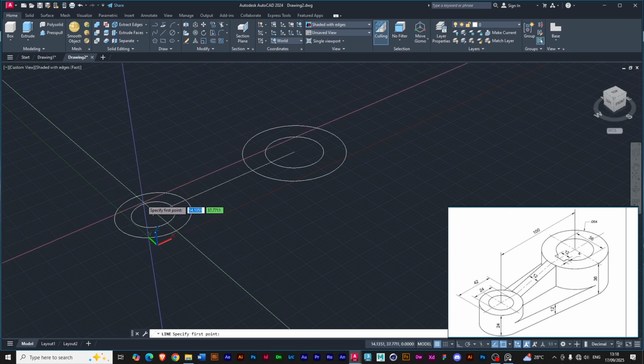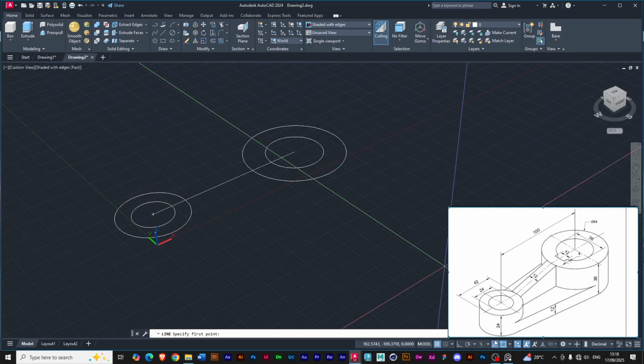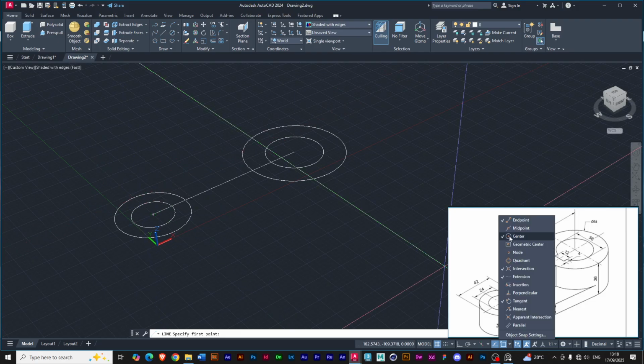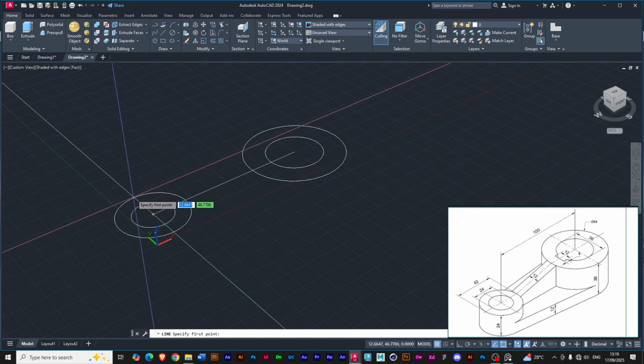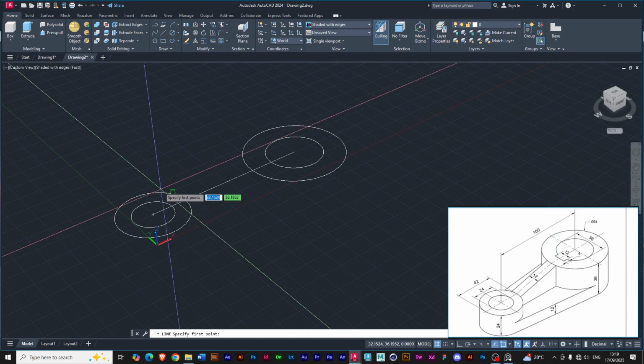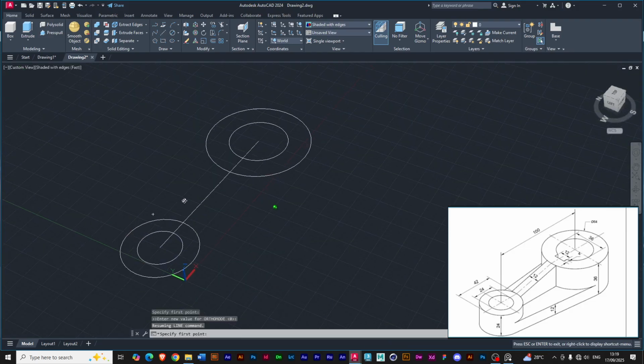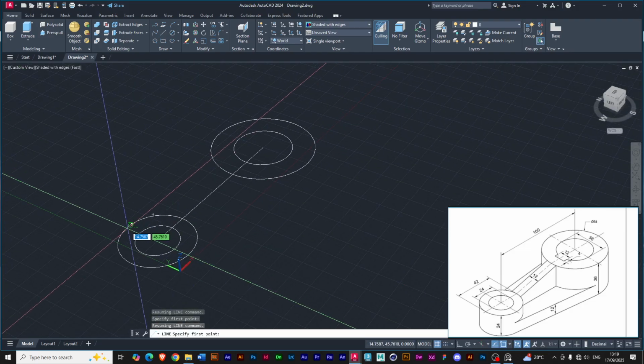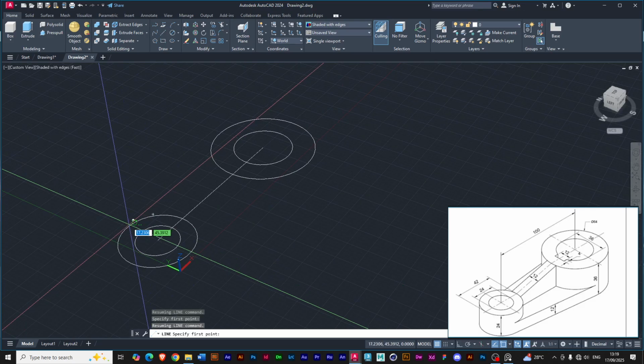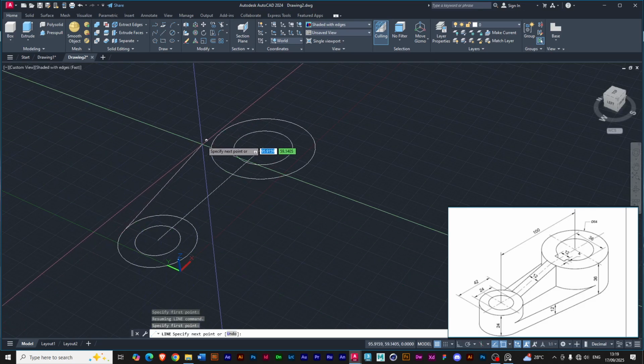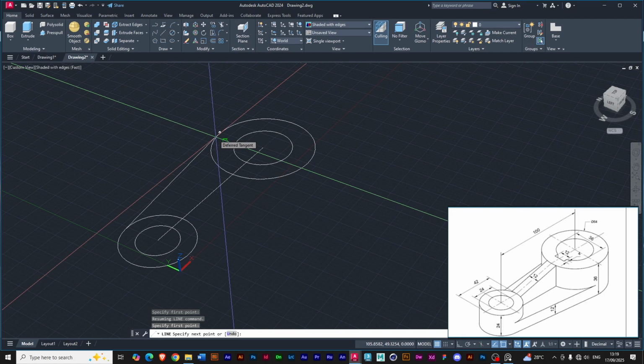If you are having issues getting the tangent, turn off the center snap as well, so that only tangents show. We just need the tangents. So pick a tangent, any tangent, it doesn't really matter where, as long as it's connected to the circle.